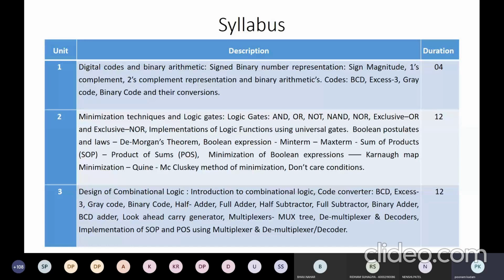So the channel that will be displayed on changing the input through the remote control depends upon both the input, that is whether you are pressing the channel up button or channel down button, and the current state of the system, that is the knowledge of the channel being viewed at that time. Such kinds of systems are called sequential logic circuit systems, wherein the output of the circuit is a function of both the current input applied to the circuit and the current state of the circuit. The current state of the circuit in turn depends upon the history of past inputs applied to